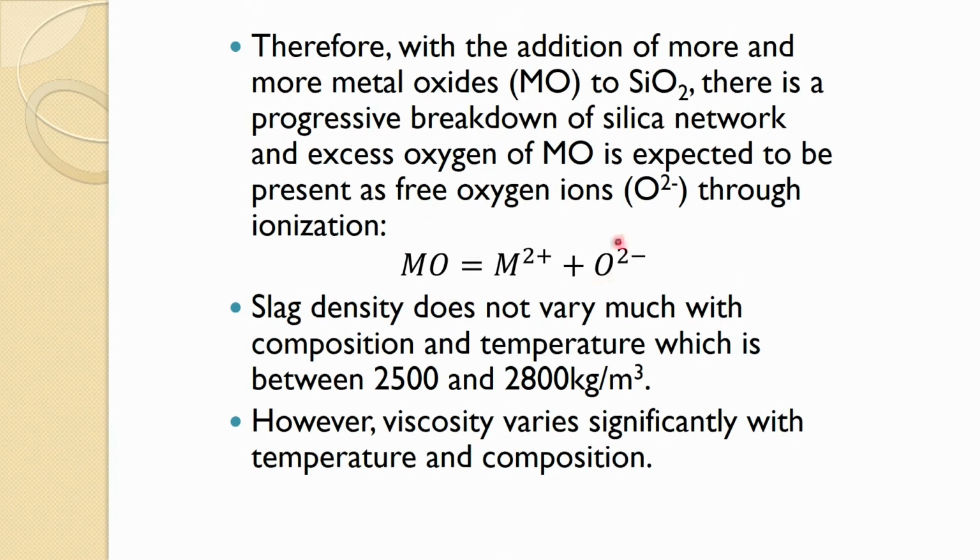This is the equation we used in defining the sulphide capacity. In steel making, similarly, you can write the equation for the phosphate capacity, which we have not discussed here, because dephosphorization takes place more in the steel making operation. So, you again represent it in ionic form.